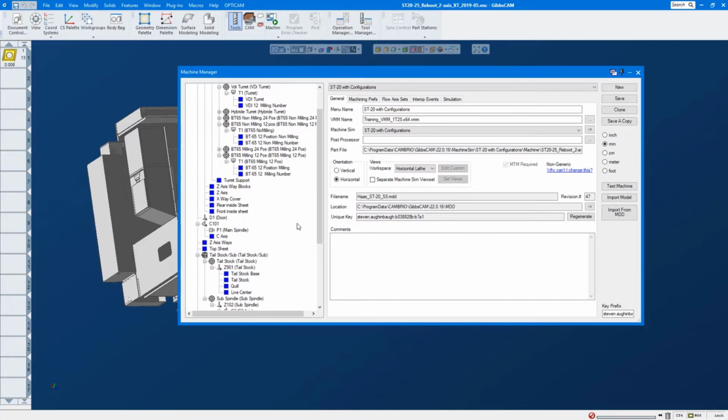But I agree with Daniel. If you're doing this for a customer, yeah, I probably would set up 15 different ones. On the milling side, it's different though. On the milling side, I would not agree with him. I would say I do want something that has an A-axis trunnion and something that's blank or has an A-axis. So you could have two different rotary tables. Actually, you could have 3 different rotary tables and just a blank axis. And I've seen that before. Guys have bolted stuff on and off. In that case, this definitely is good. For turning, not so much.